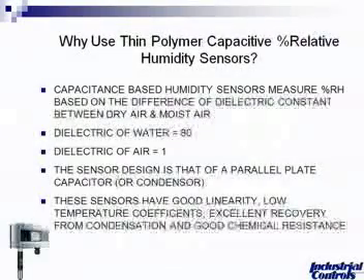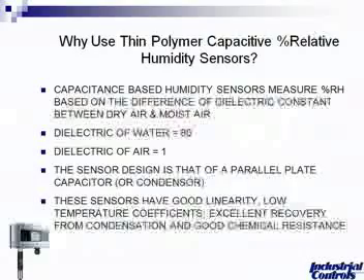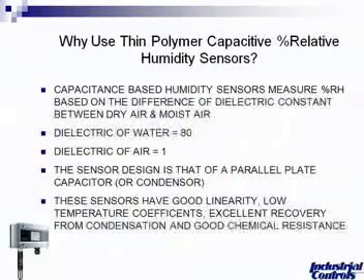The dielectric of water is 80, and the dielectric of air is 1. So basically the design here is a parallel plate capacitor that gives you good linearity, good temperature coefficients, and good recovery from condensation on some capacitive sensors, not all.